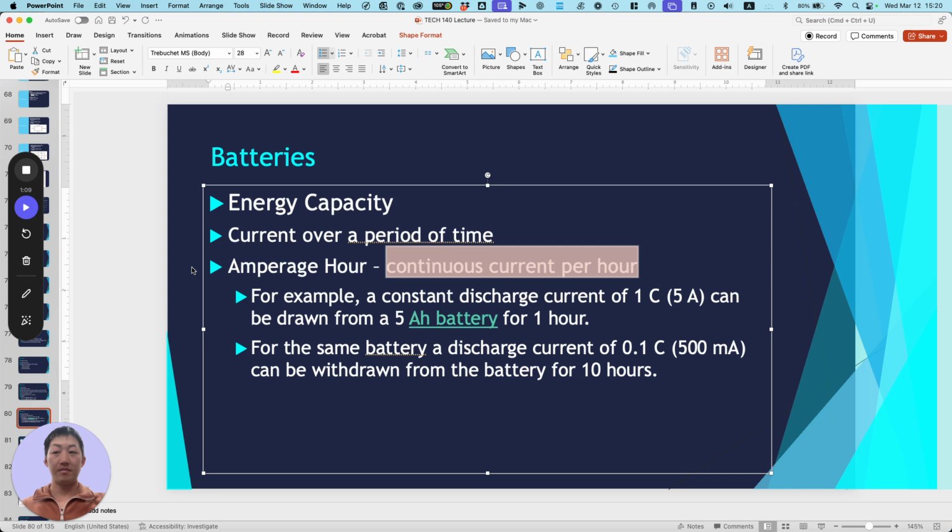Let me see if it matters which side we mount it, because the motors, right? The IMU has a direction. It does, you're right. So the IMU, or inertial measurement unit, does have a direction. If you look here, I found a little yellow arrow. Do you see that? Yep. That tells you what forward is.